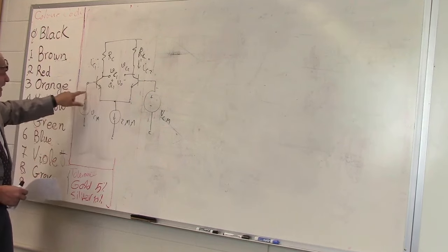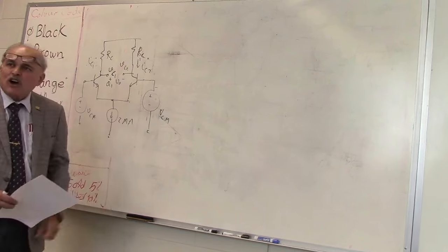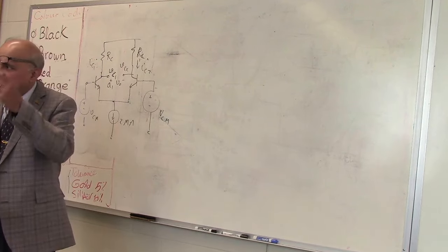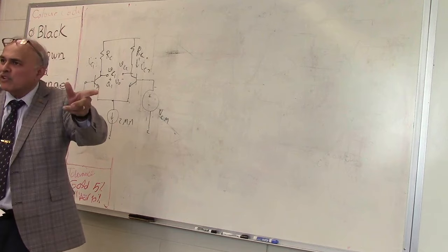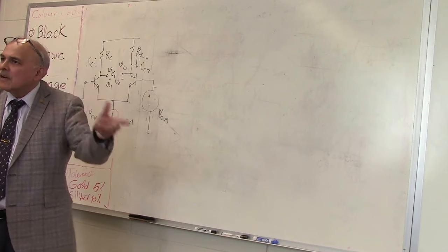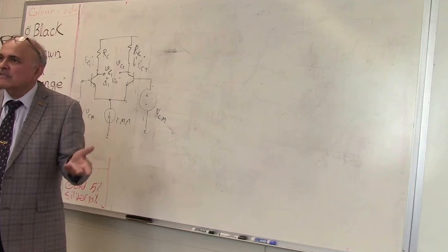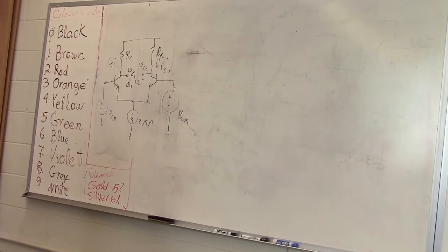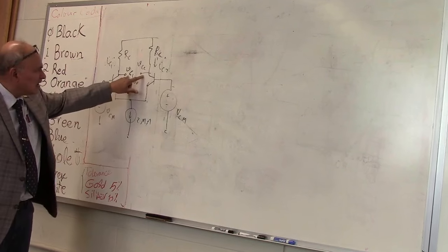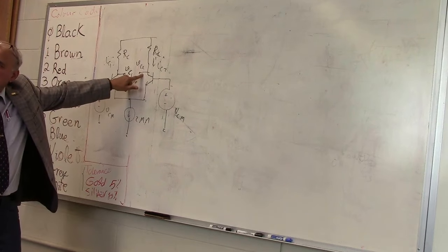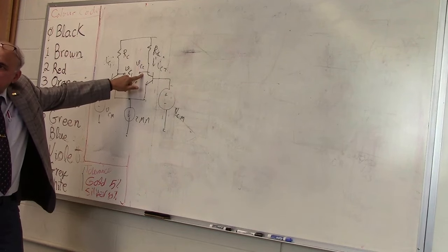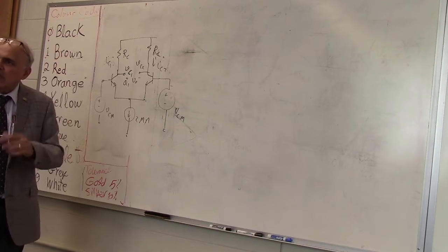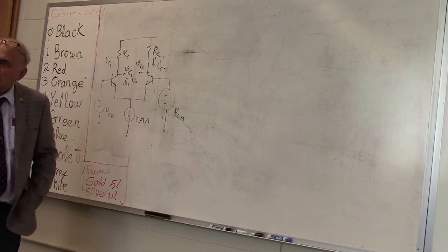0. So applying the same voltage, or what we call a common mode voltage, to both the bases will not result in any output voltage differentially taken between the two outputs here. Right? So this thing does not amplify so-called common mode voltages. Have you heard of common mode voltage before?